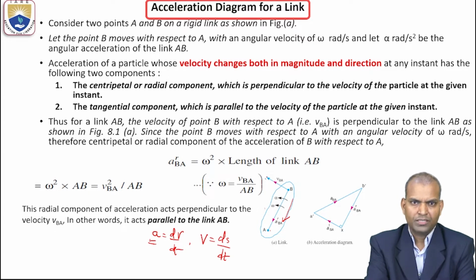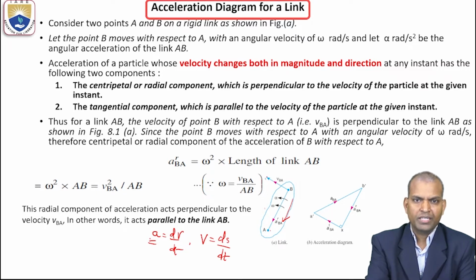That is very important. If an acceleration diagram is to be drawn, that means the velocity diagram should already have been drawn. Otherwise, we cannot draw the acceleration diagram.